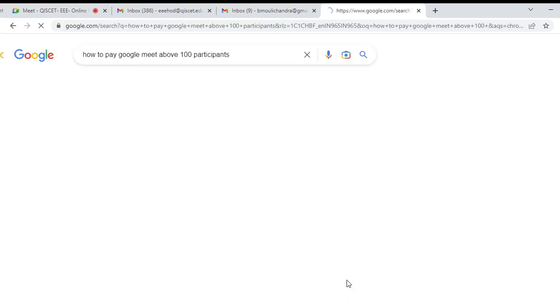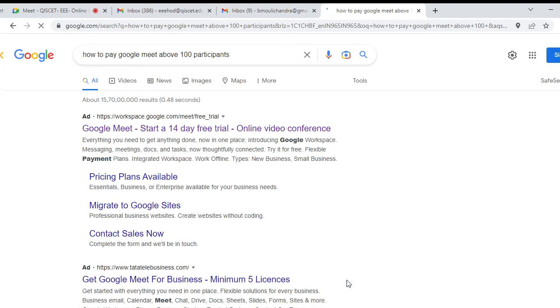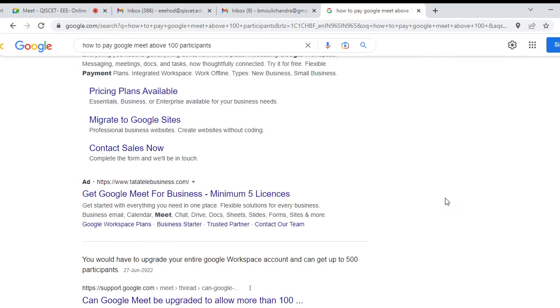So this is the first configuration. Here S15 is open and the other switches are closed. Closed is indicated by 1 and open is indicated by 0. For this one we can have the stability indicator. Here we have calculated the stability by means of some L index, which can also give you the stability value for each of the buses.